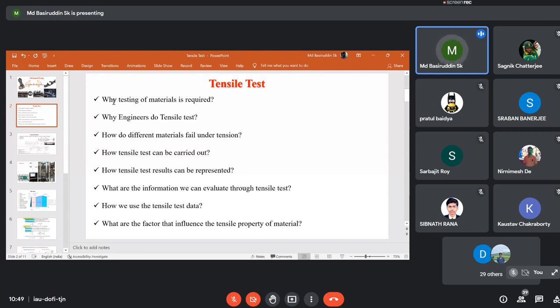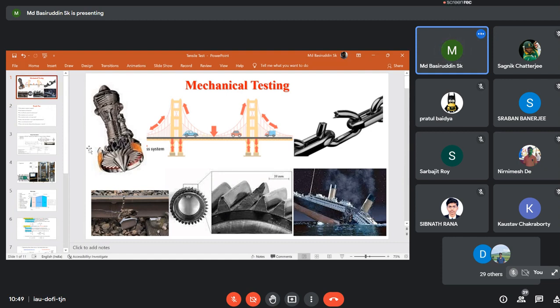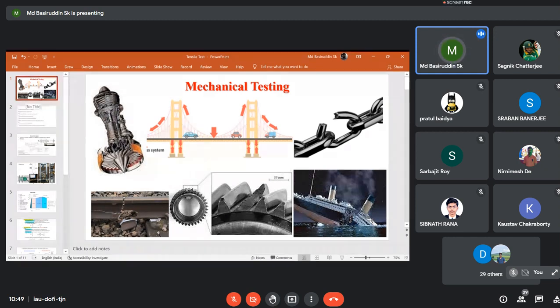So when materials are designed, let's say for bridges or buildings, or the aeroplane engine blades, they are designed considering the elastic properties, because engineers will not allow the material to extend or deform plastically, in such a way that permanent deformation is retained in the material.